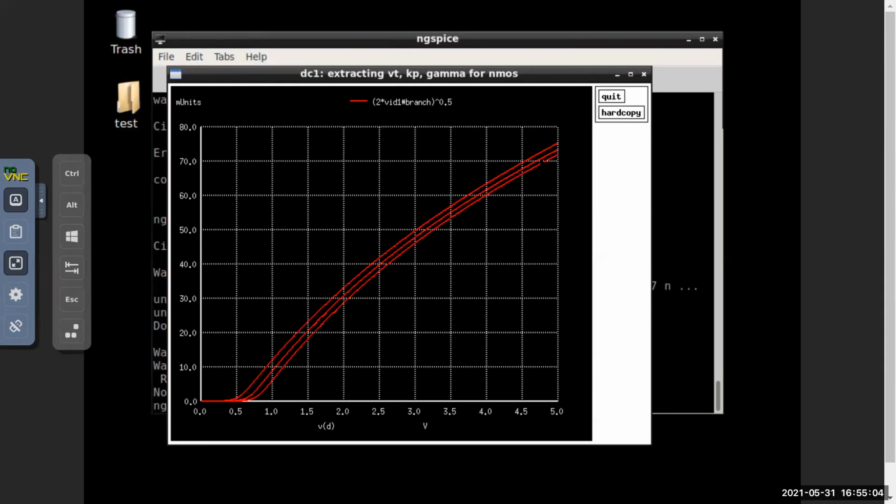Now, this is actually 0.5 micron. You typically don't see a huge amount of high field short channel effects, but you can see that you're actually seeing that. So to extract the parameters, we'll stay in the linear region and not go here, because if I extract from here, then your VT is going to be negative, which is unrealistic. So we are going to remain in the long channel regime and then extract the parameters.